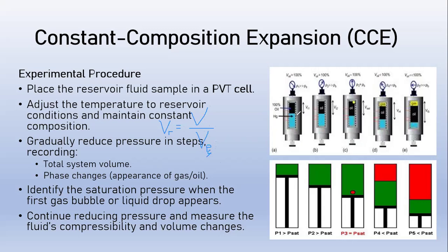So as they are doing the experiment, for each pressure step they keep on recording the volume of the hydrocarbon for each respective pressure, including that of the bubble point. But for you to calculate the relative volume, you take each volume of the pressure step and divide it by the volume for the saturation pressure, or let me say bubble point pressure with regards to oil.